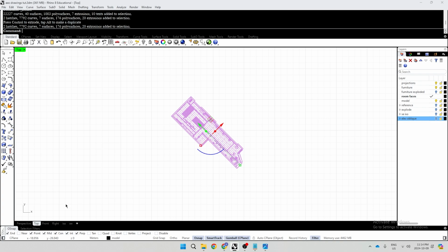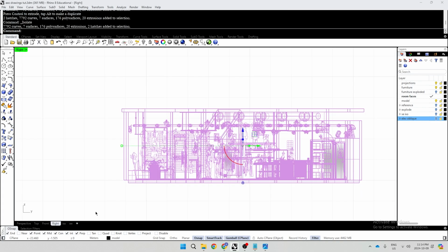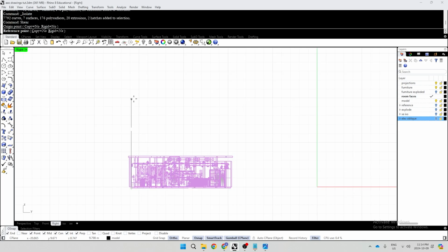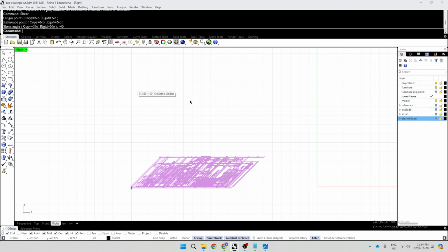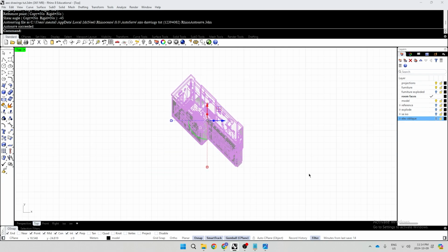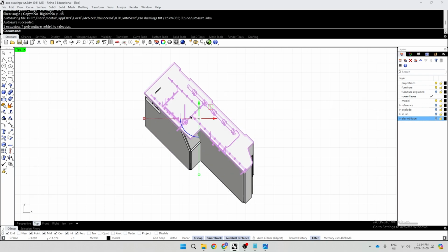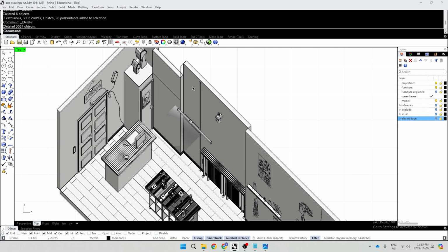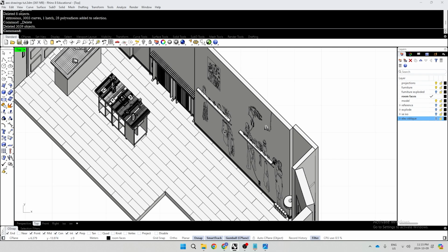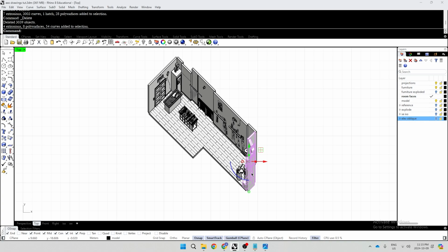Now we want to rotate it by 45 degrees. And go into right view. Shear again. Take the origin point, point up to the z-axis, shear by negative 45 degrees. Okay, and go back in the top view and delete all the sides you don't want. And you should see a plan oblique drawing.